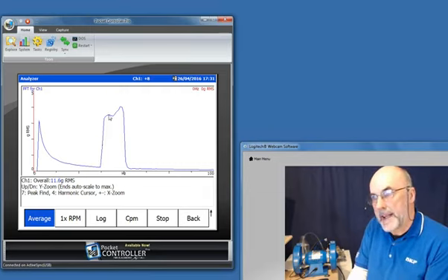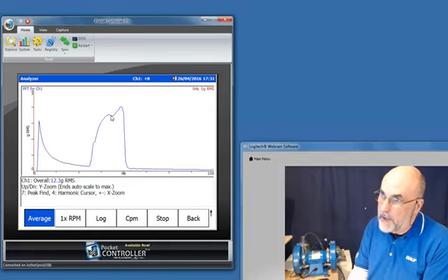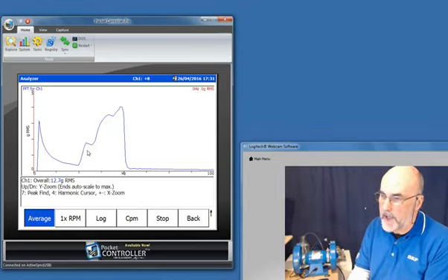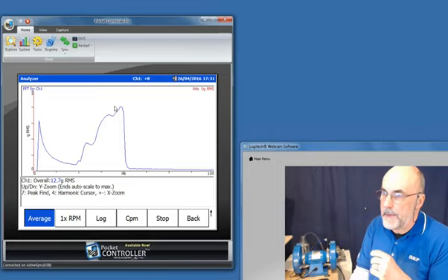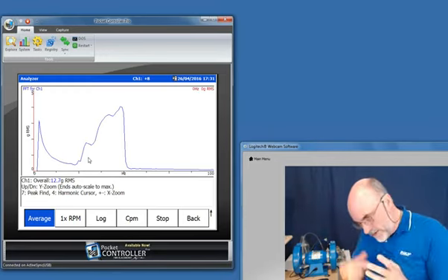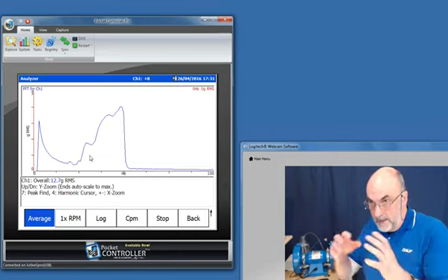And right now I can feel my desk is starting to vibrate because the levels have gone up. It's hitting the natural frequency of my desk. And you can see how the peak hold average is keeping a record of where the levels have been versus time. So it really is a quick and dirty way of doing a rundown. The levels were coming down, as we would expect, but now they're going back up as it hits a natural frequency of my desk. They're coming down, they're going back up. So you can see all these areas here where they go down, because the unbalanced forces are related to the forces and the displacements.